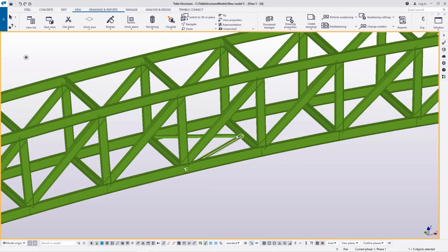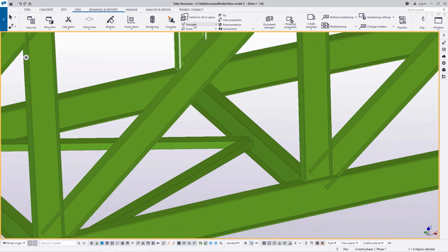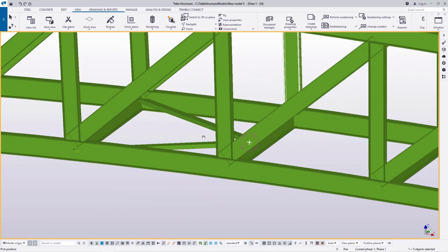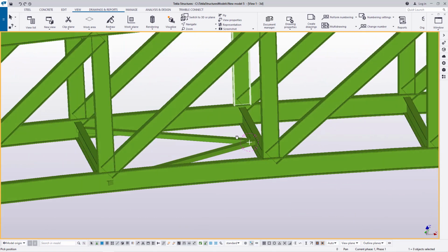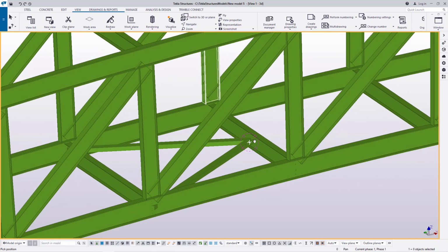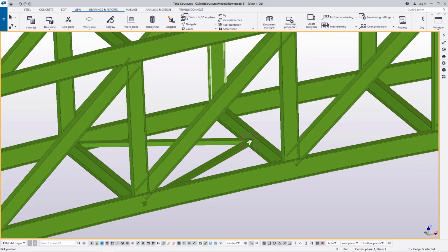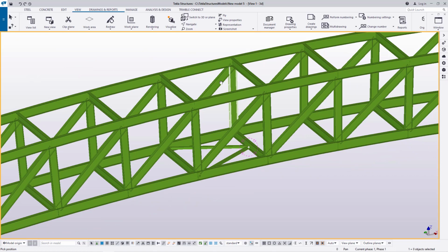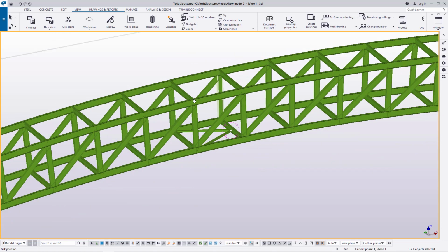Now, if you take a look here closely, you can see some braces I've already placed inside here. So I want to populate these braces along this curve, and we'll just use the same method that we used previously. First of all, I'm going to put the marking points that will guide me in populating these bracings along this curve. Also, today we're going to place the columns that will be sitting right on top of these curves. On top of those columns will be our footpath, the footbridge floor itself.